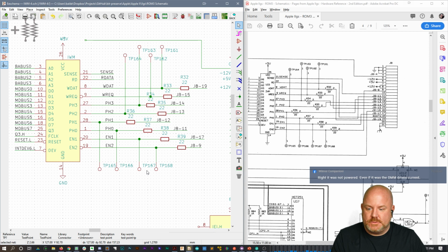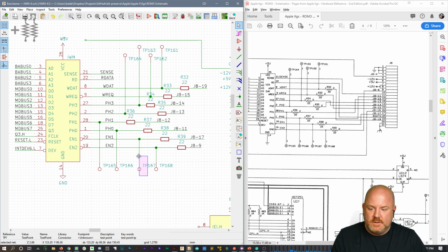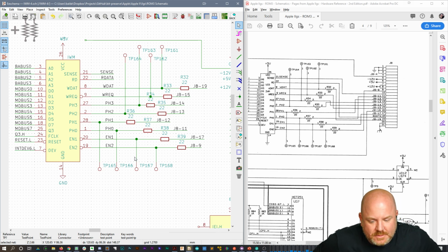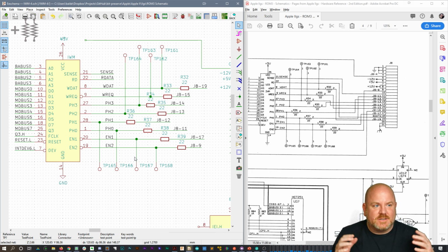He said, I'm measuring pull-up resistors. And since we spent all this money on this new 6 gig scope with these fancy 6 gig probes, we're using those. I'm like, okay, so you're using a 6 gigahertz probe for a DC measurement. That's brilliant. He was verifying with the voltage.